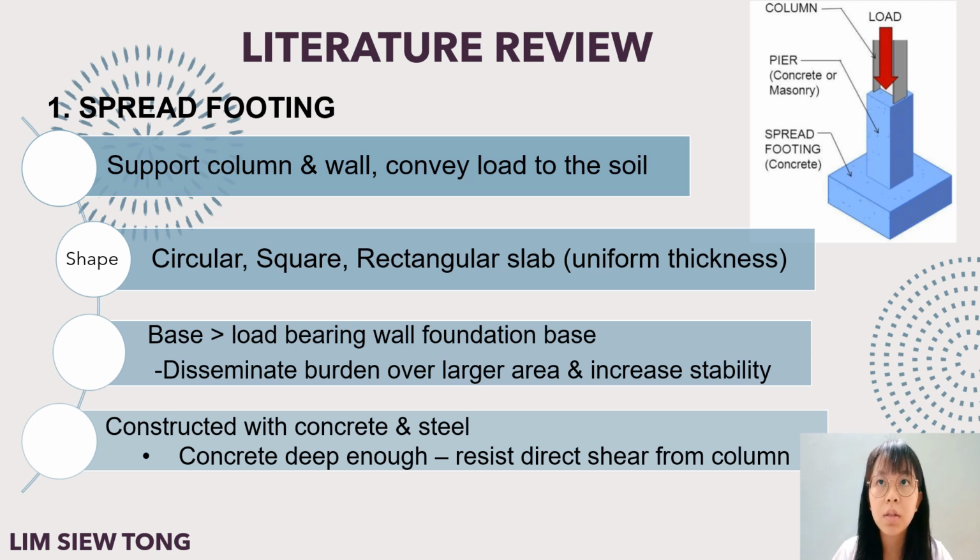Spread footings are utilized to support columns and walls, then convey the load coming to the structure to the soil below it. They may be circular, square, or rectangular slabs of uniform thickness. Their base is wider than a typical load-bearing wall foundation base. The wider bottom disseminates the burden over a sizable area, adding stability to the building.